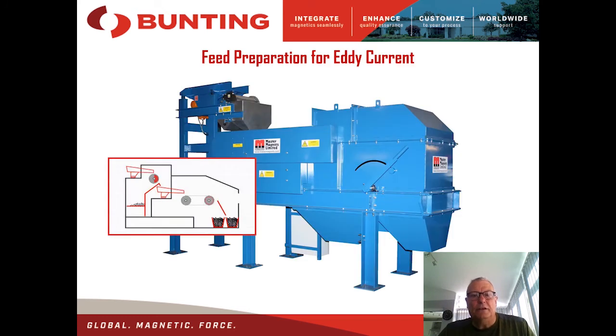Here we have the feed system for an eddy current separator. So we would feed onto the vibro feeder here, which will feed onto our magnetic drum separator located here. Our magnetics from the drum separator will be discharged here. This might be a ferrite separator, which is low intensity, if our contamination is large nuts and bolts and tramp iron, mild steel. It might be a rare earth drum if we have finer particle size and some material that's not liberated that has a medium magnetic susceptibility.